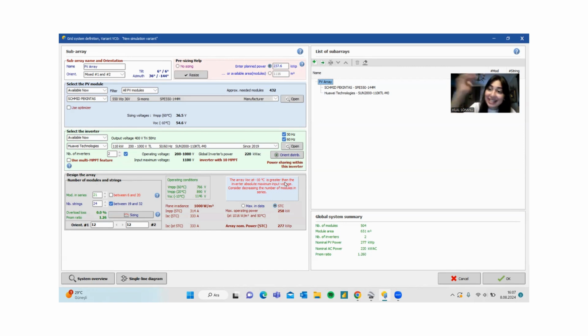We are exceeding it when we connect the panels in a string and strings to strings. After we connect all the strings together, it says your open circuit voltage at -10 degrees is greater than your inverter absolute maximum input voltage. But what that means for us, we will discuss these kinds of errors and warnings in the upcoming video.